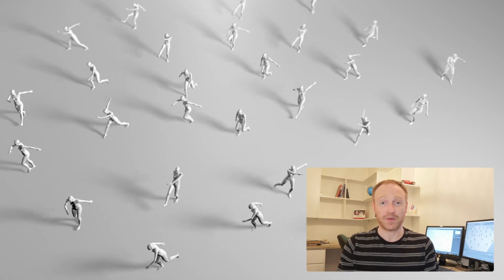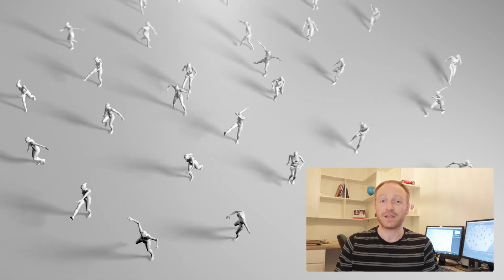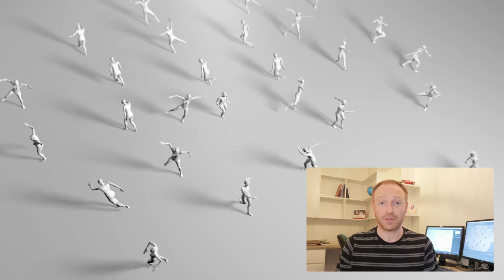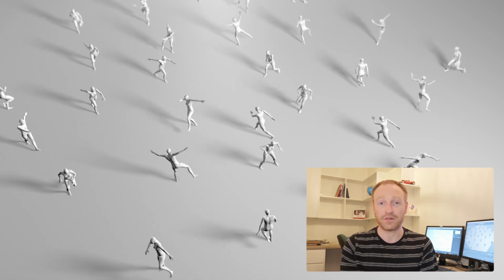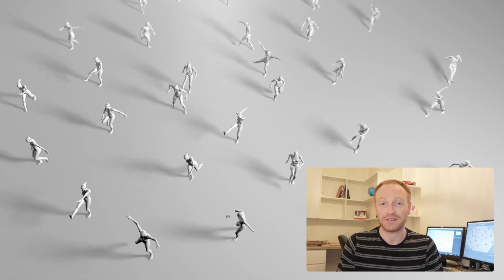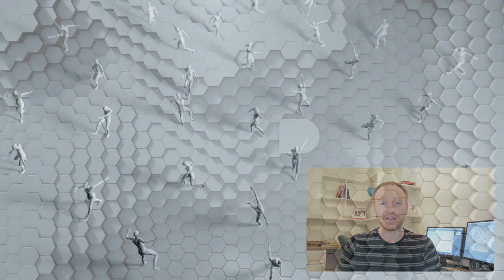We're also going to be talking about motion blur. We're going to be setting this up using the physical renderer in Cinema 4D, and we're going to be creating some motion blur. Now this is very heavy on render times, so you guys might be aware that you can actually set up a fake motion blur in After Effects. We're not going to be doing that. We're going to be doing the actual Cinema 4D motion blur. So be prepared for a bit of heavy render times if you do want to render out this scene. So let's get started on this. Here we go.